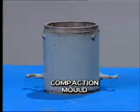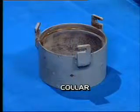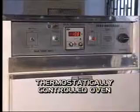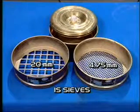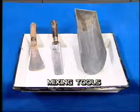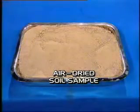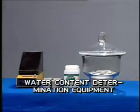The equipment required for conduct of this practical includes compaction mold, detachable base plate, collar, metal rammer of 2.6 kg, balance, thermostatically controlled oven, IS sieve of 20 mm and 4.75 mm, steel straight edge, mixing tools, graduated jar with water, air dried soil sample, airtight container and water content determination equipment.